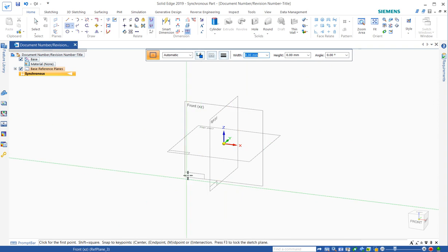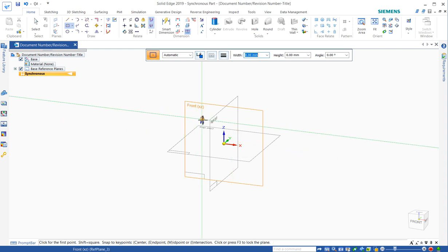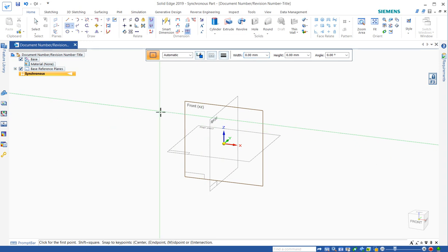If you hover over an element other than a plane, you see a plane already has orientation, so you really just hit the plane, and X will be the lower left, where this is your lower left corner on a plane. That's the little indicator there. But if you hover over a different element like this coordinate system, you can tap N. You see the little green element showing up, so that will change what is the x-axis. More on that later. But I establish a plane, and then I just draw.